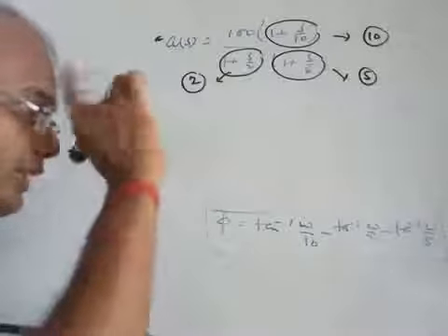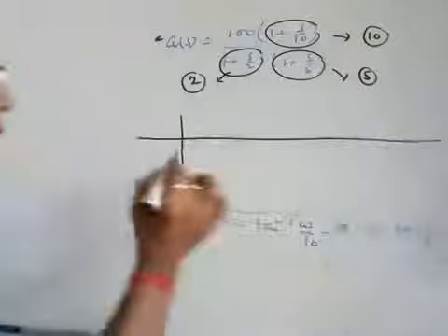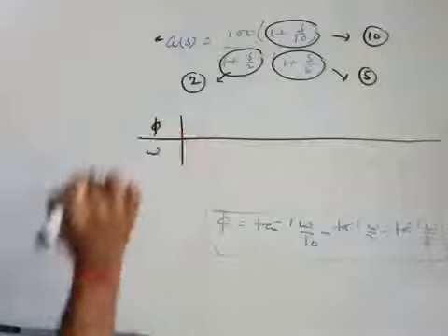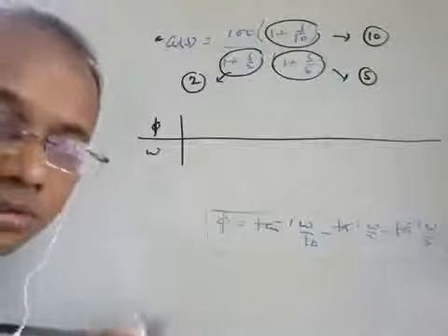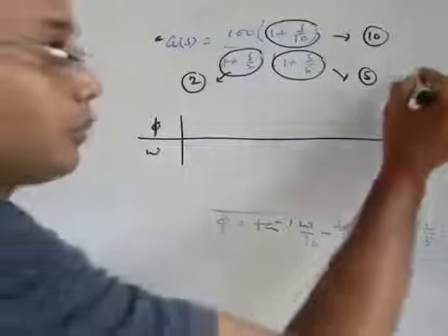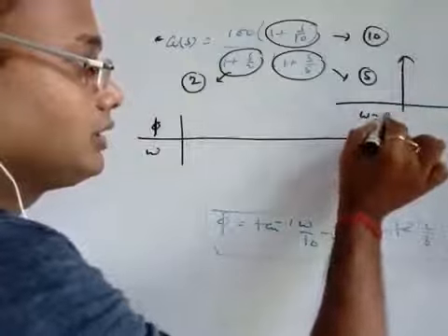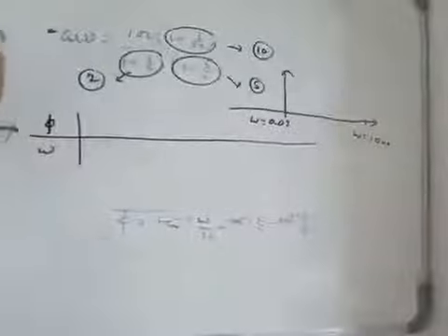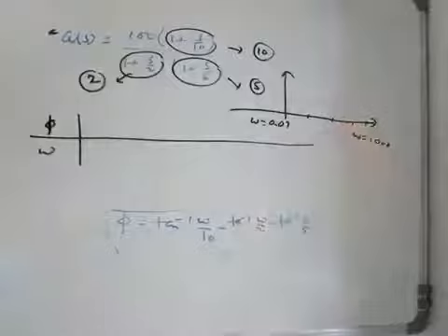Because when you make the table, we get a table like this. What is the procedure? This is your omega and this is phi, right? So what are the different values of omega we have to take to get the curve? In your Bode plot, this is your semilog graph paper, from omega 0.01 to omega 1000, and in between there are 5 divisions, right?